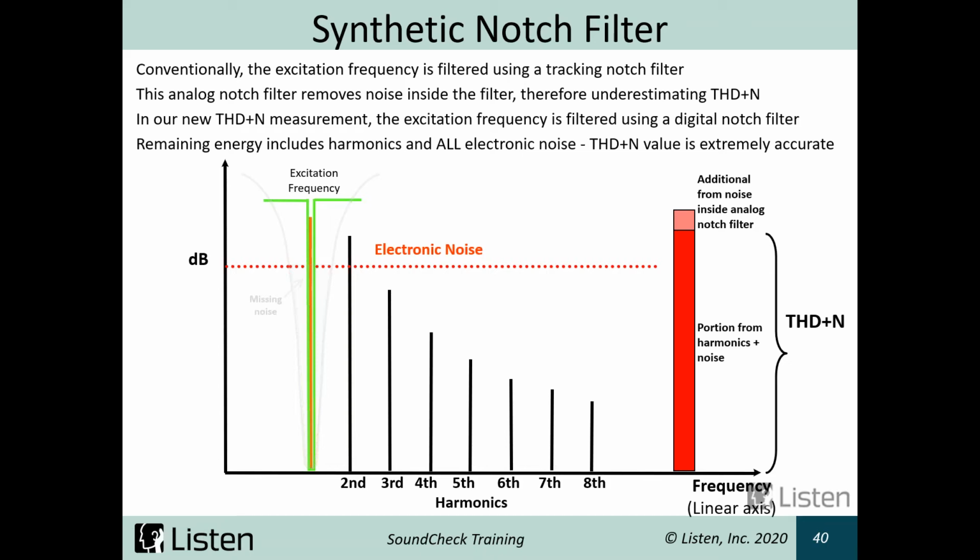In general, THD+N is a good measurement for electronic devices. But if you're trying to measure transducers, like a loudspeaker, then the background noise is going to be so much higher than the distortion, measuring THD+N isn't really an appropriate measurement. For something like that, you'd care more about THD or rub and buzz, perceptual rub and buzz, etc. The noise from the background, the noise from just the room you're in, is going to skew the measurement so much, it's not really something that's going to be very helpful to get data back from.